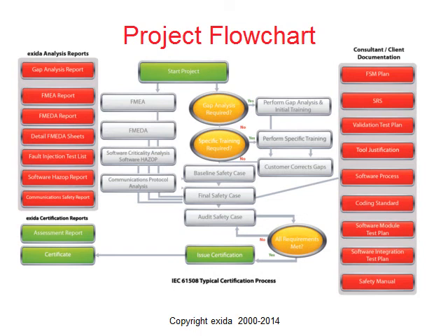If we look at a typical 61508 project, there's going to be, in the center, on the left side, the analysis of the hardware. We have a software criticality analysis, communication protocol analysis to understand, document, and show how the device is working. Then on the right side, there are a lot of process-related things, which will deal with the engineering process, management of change, impact analysis.